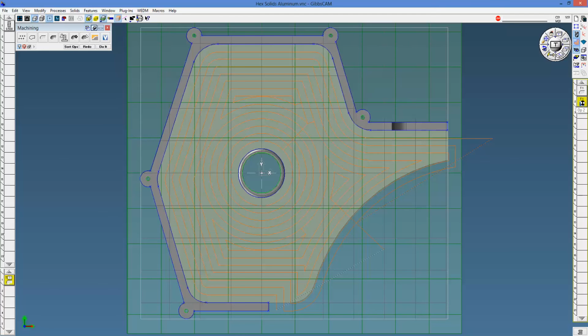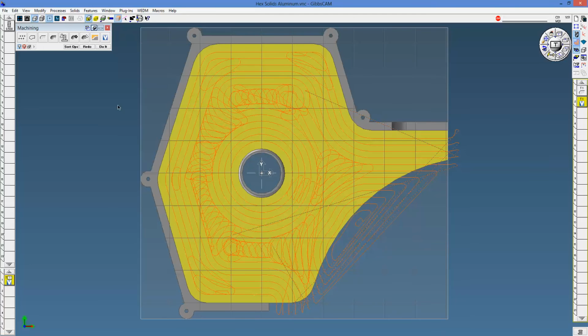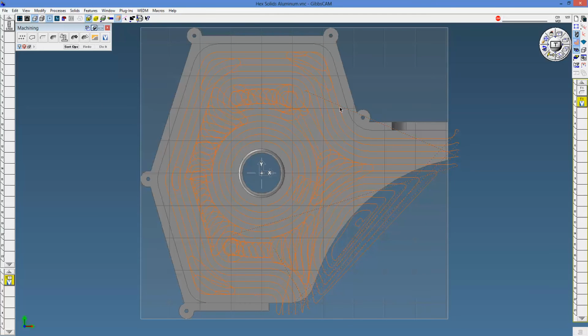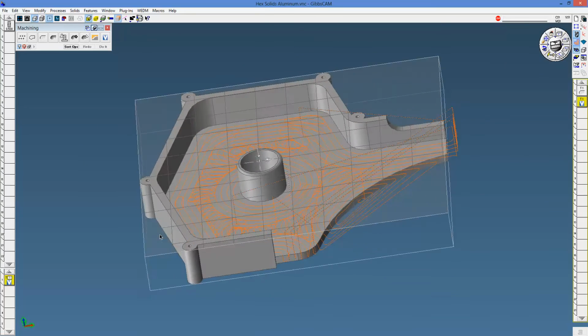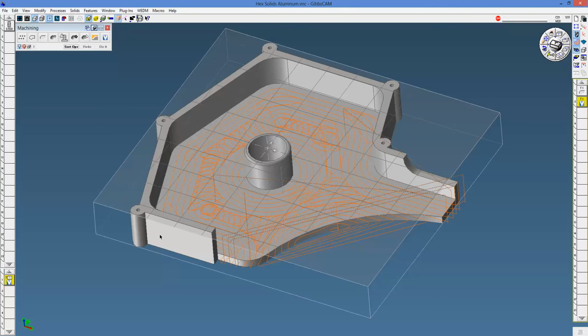Now let's look at the VoluMill toolpath, and you'll notice it looks different, right? We've got loops. You'll notice also there are no sharp edges, so it never slams into a corner. It never all of a sudden takes a right turn. Everything's very smooth. Everything's radius. What VoluMill does is set a volumetric removal rate, that is cubic inches per second of chips flying out of the machine, and it tries to maintain that constant volumetric removal rate. So that's one thing that it does.